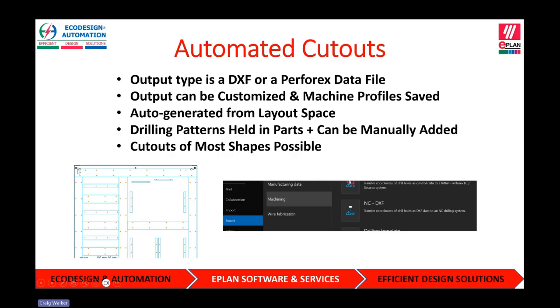So once you've actually placed all your DIN and duct in ProPanel, I'm not going to go through the placing of it today, but it's pretty much snap on a corner, drag it the length, and click again. It'll actually automatically place the drilling holes as per your drilling pattern. You can see it's even moved a few of them to dodge the holes in the mounting panel. And this will allow you to automatically generate your 2D drilling patterns and produce those outputs straight away.